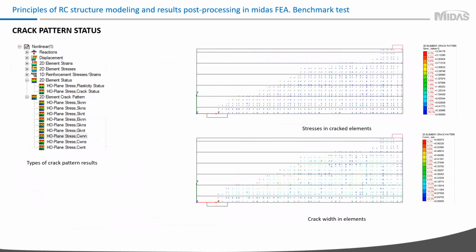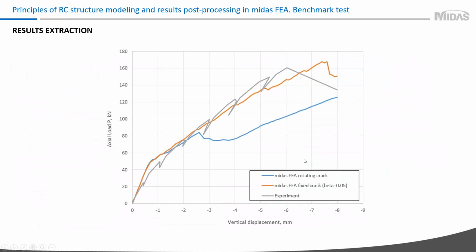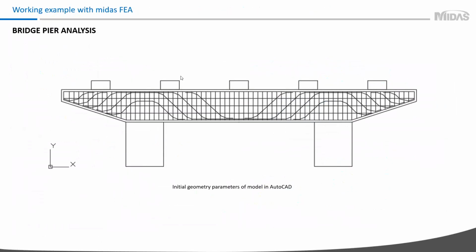What if we don't sew faces and use the after mesh option? The idea of sew is next. For example, I have separate faces here, and for this part I would like to use a very good mesh with a very small size of elements, because I investigate this part of the model. But for other parts, I don't need a quite good mesh. I can use a coarse mesh.